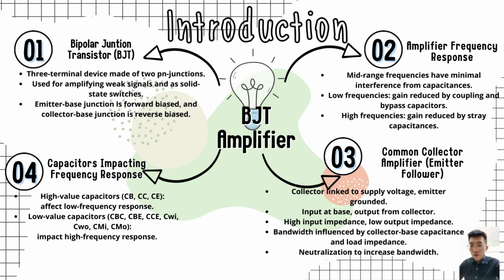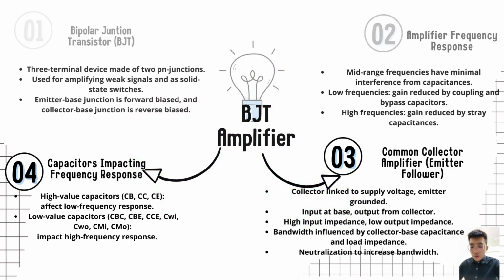And the last is the capacitors impacting frequency response. The higher value capacitors CB, CC, CE affect the low frequency response. The low value capacitors CBC, CBE, CCE, CWI, CWO, CMI, CMO impact the high frequency response.